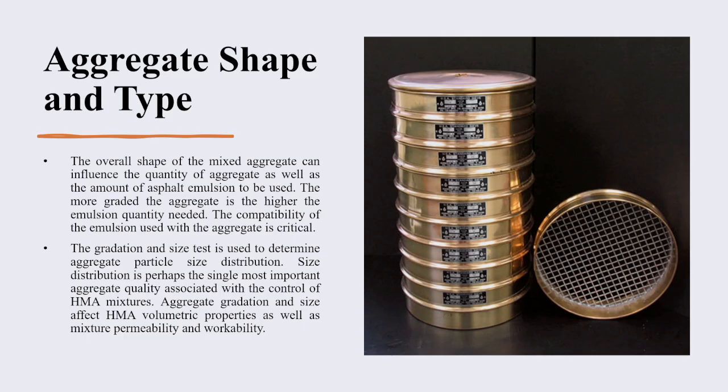What is the safe size if you are in a materials class that separates between coarse and fine aggregate? Let's say you work in a concrete batch plant, or you are in the business of rigid pavement, and you're talking to the technician, or your boss is talking to you, and he mentioned the word, how much coarse aggregate do we have? What does he mean by coarse aggregate? It is aggregate retained on sieve number 4.75 millimeter. That's the dimension. Or number 4 in the number. So sieve number 4, which means 4 openings per linear inch, or 4.75 millimeter.